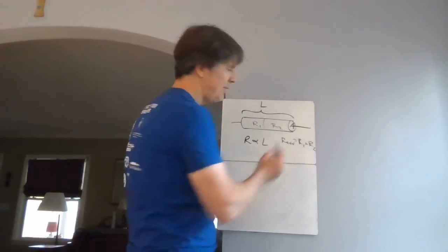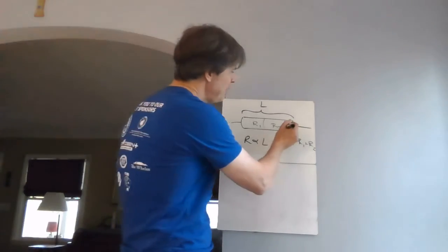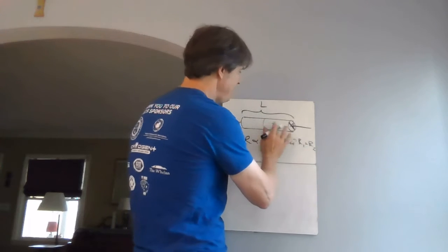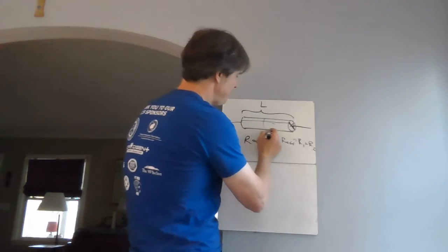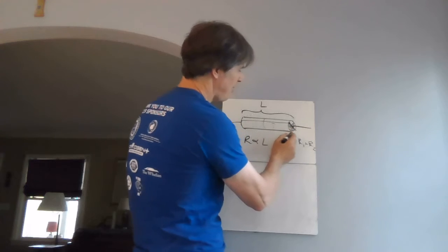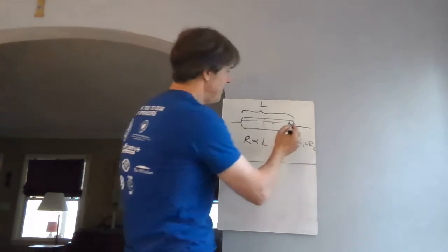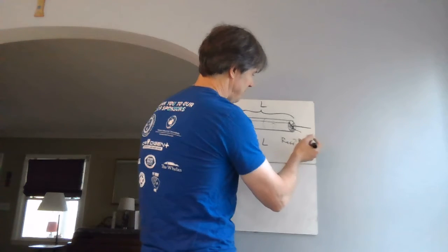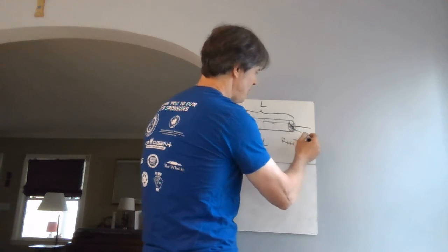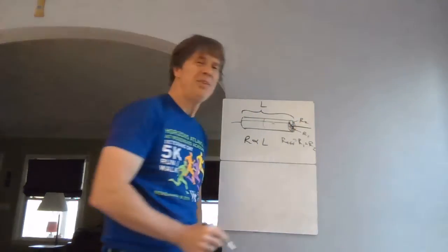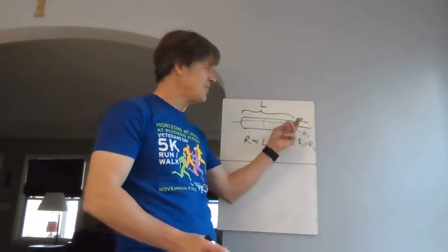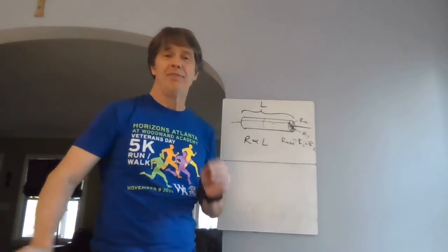Here's the cross-sectional area of the thing. What if you imagine splitting the area in two? And then you could talk about maybe a semicircular cross-section, half-cylindery thing that's got a small area, whatever it is, and it's got a resistance R1 and the other one's R2. Can you see that those two things are in parallel? That means that the total resistance, in fact, would be half of either of them alone.